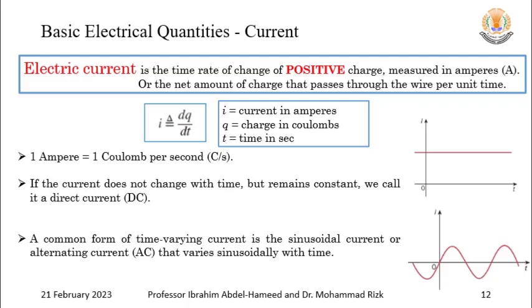And we agreed we are going to study steady state circuit analysis. What does steady state mean? The source will remain like that forever, and a sine wave will remain a sine wave forever, with no change in the peak value or the frequency. If you have 10 cycles of AC and you cut each one and put them on top of each other, they will be identical. Identical means no change, steady state. Clear?